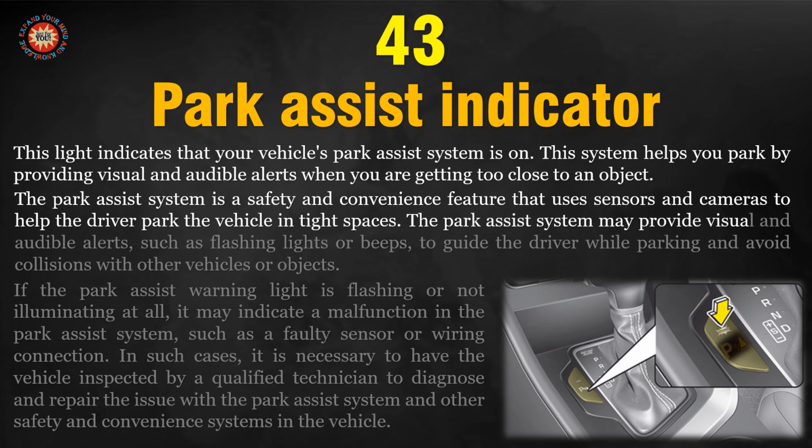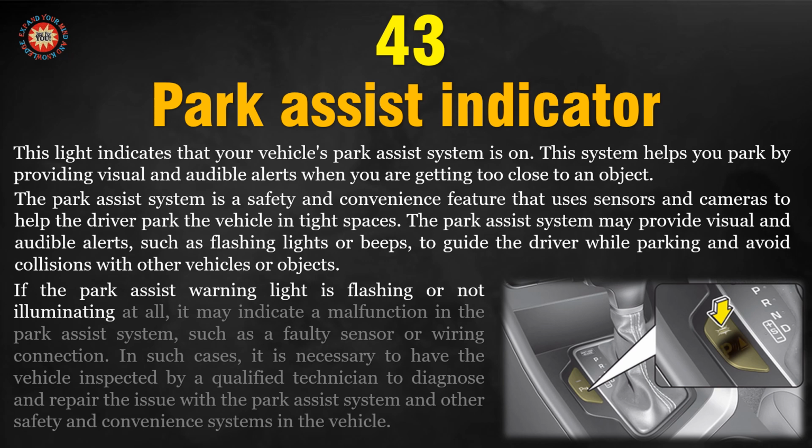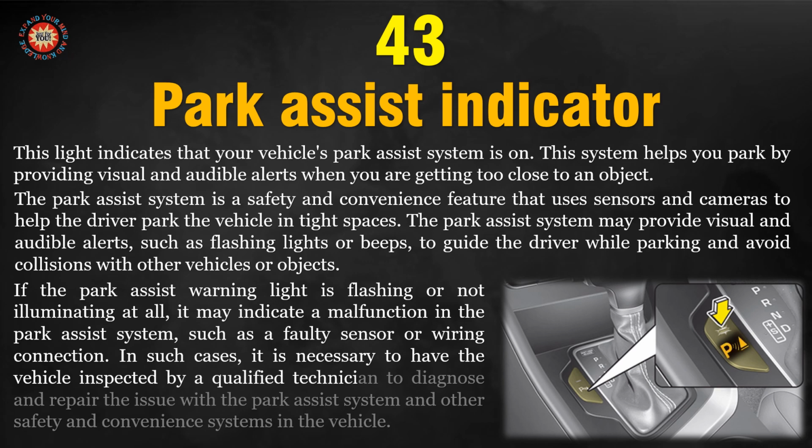The park assist system may provide visual and audible alerts, such as flashing lights or beeps, to guide the driver while parking and avoid collisions with other vehicles or objects. If the park assist warning light is flashing or not illuminating at all, it may indicate a malfunction in the park assist system, such as a faulty sensor or wiring connection. In such cases, it is necessary to have the vehicle inspected by a qualified technician to diagnose and repair the issue with the park assist system and other safety and convenience systems in the vehicle.